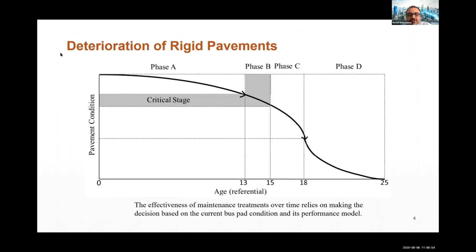It refers to the combination of partial repairs on the basic structure of the road and strengthening its surface. Phase D is a decomposition phase. When no intervention is applied at any time in previous phases, the pavement reaches the point of breakdown and failure is widespread for both the pavement surface and the basic structure. Decomposition of the road is the last stage of its existence and can last several years. At this phase, the only solution is reconstruction of the pavement. There is no efficient maintenance plan for phase D.